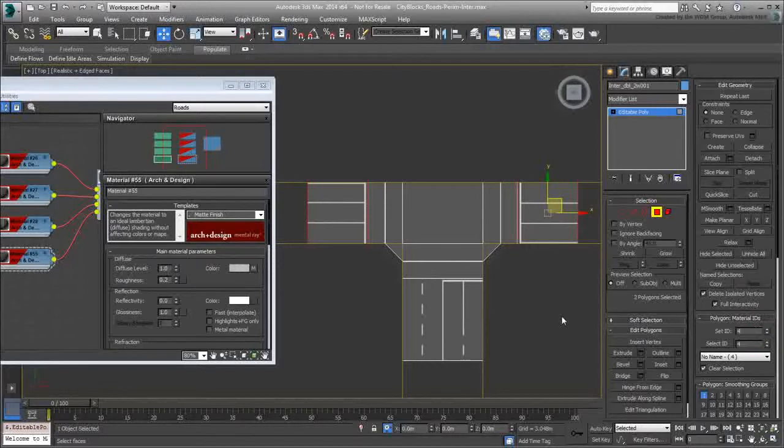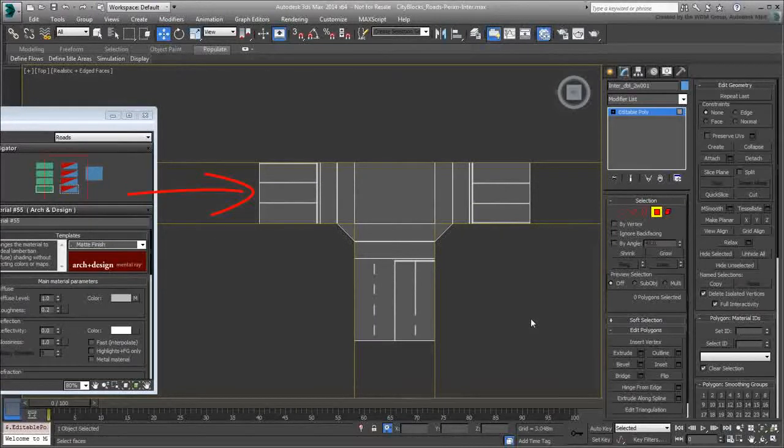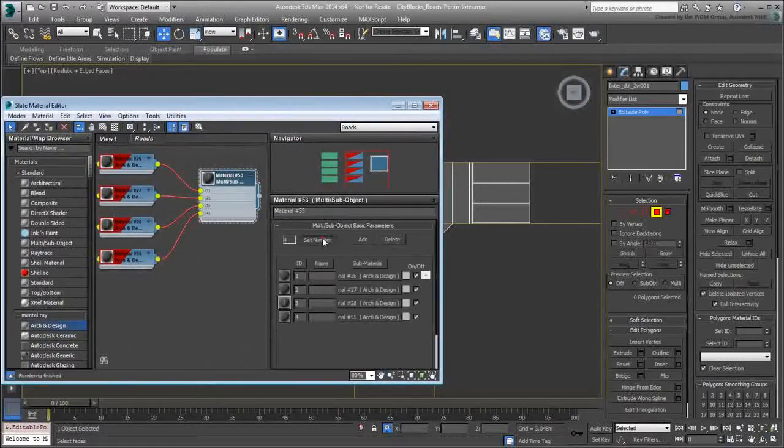Well, this works for one area, but not the other. Traffic flow is coming from the left, so it makes sense to have a stop line as displayed here. However, on the right side, you need a different kind of bitmap, one that still has 3 lanes, but with intermittent dividers and no stop line. So, use the same method as before to add a new submaterial.